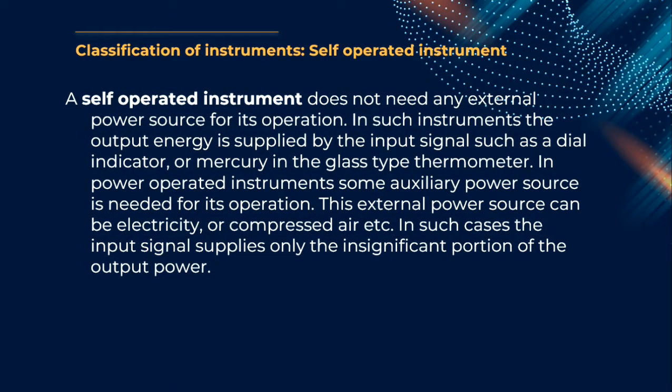Next is a self-operated instrument. Self-operated instrument does not need any external power source for its operation. In such instrument, the output energy is supplied by the input signal, such as dial indicator or mercury in a glass type thermometer.